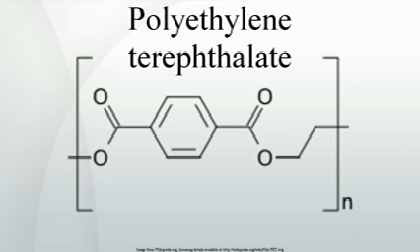Processing examples for recycled polyester. Recycling processes with polyester are almost as varied as the manufacturing processes based on primary pellets or melt. Depending on the purity of the recycled materials, polyester can be used today in most polyester manufacturing processes as a blend with virgin polymer or increasingly as 100% recycled polymer. Some exceptions, like BOPET film of low thickness, special applications like optical film, or yarns through FDY spinning at greater than 6,000 meters per minute, microfilaments, and microfibers, are produced from virgin polyester only.